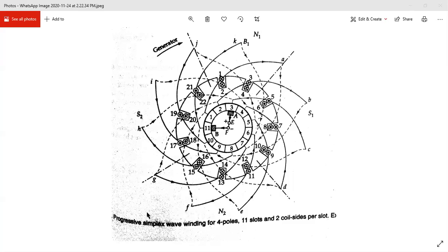Yes, you will see that if you short 11 and 6, the whole coil that has caused this problem will be bypassed, isn't it? Yes sir. Okay, so either you can place the brush on 11 or 6, because you cannot place the brush between K and B, because that comes in the overhang position of the coil. You don't have any access there.